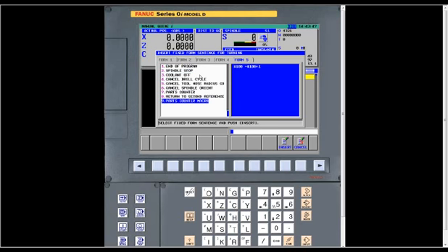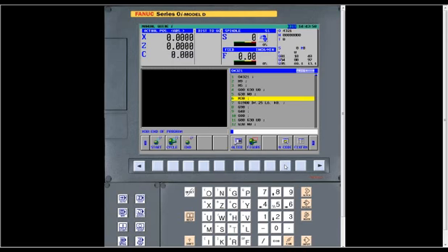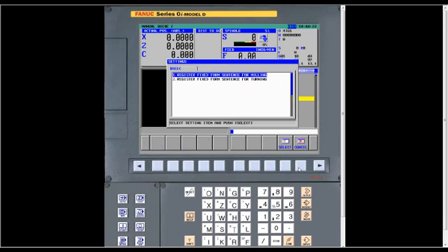I've got a parts counter macro. I can just paste that into any program. And then when you actually want to put that within a program, you just press insert, and it actually adds it to a program. Now, I showed you my fixed forms, and after this is over, if you need to, contact me direct. I can help you develop these fixed forms. But then to actually make them yourself, if you go right shift until you see a soft key called settings, you go into that. It takes you into the basics where you can either set them up for milling or turning.